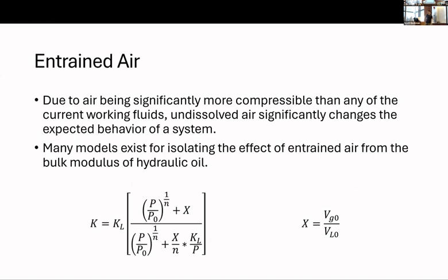A lot of models exist for how to isolate the effect of the entrained air from the bulk modulus of specifically hydraulic oil. And so we took some of those models and directly plugged them into our system and got some results that looked really good initially and now look a little bit less good, but I will present them here shortly. And so here on the bottom left, you can see one of the models where the initial K for bulk modulus is the combined bulk modulus, you could say, for both the air that is entrained in the fluid and the liquid that we're working with.